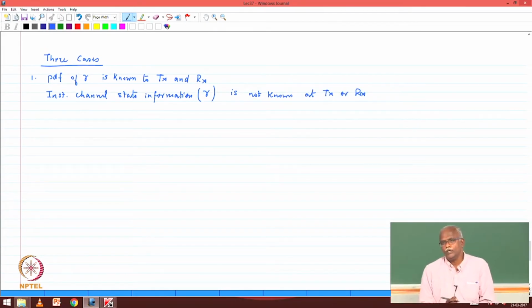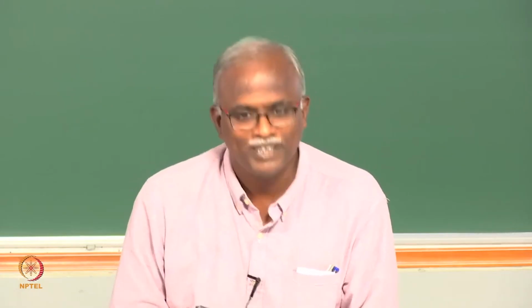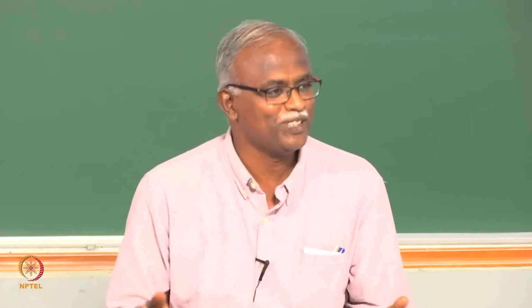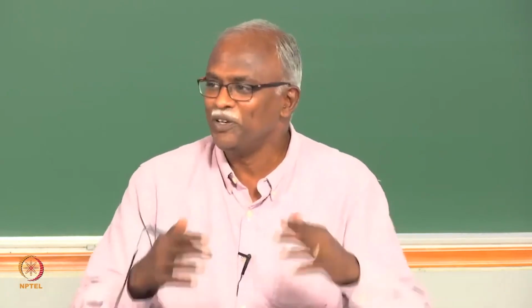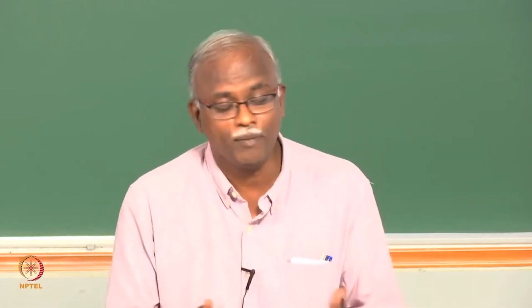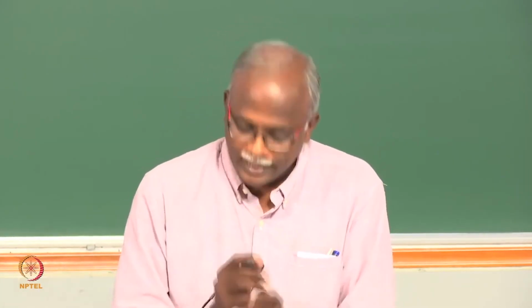Now, if you don't know the SNR, what would you do in a practical scenario? You'll measure it. But in information theory, it's perfectly fine to assume that you don't know the SNR, you don't want to measure it. You just say, okay, if I have only the PDF, what do I do? How do I achieve capacity? And it turns out that, according to the information theory experts, this is a very, very difficult problem because you don't know what the instantaneous SNR is.